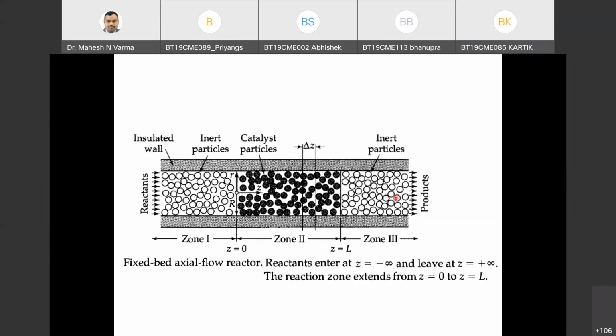So the total, combined energy flux. Yes, sir. Whenever there is a flow, this is the thumb rule: we start the problem with combined energy flux, and then we add all the assumptions. Because here there is a flow and we are discussing temperature variation in the direction of flow, we'll start with a combined energy flux. This is the first thumb rule.